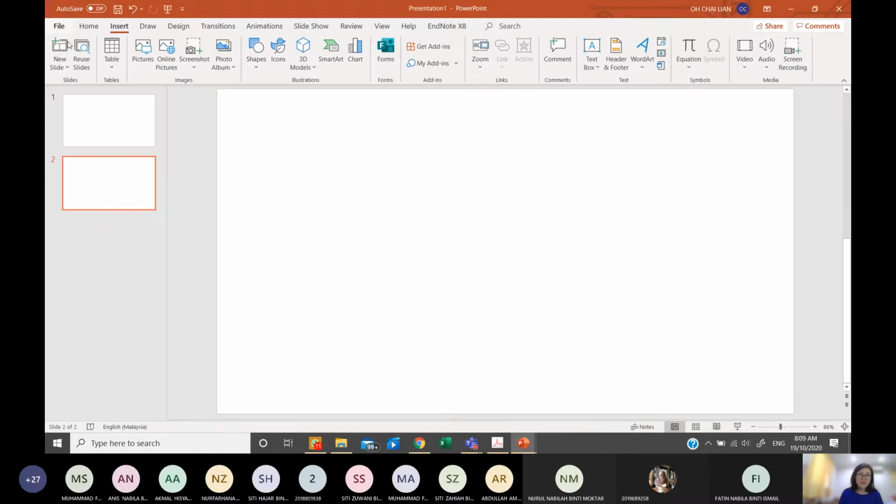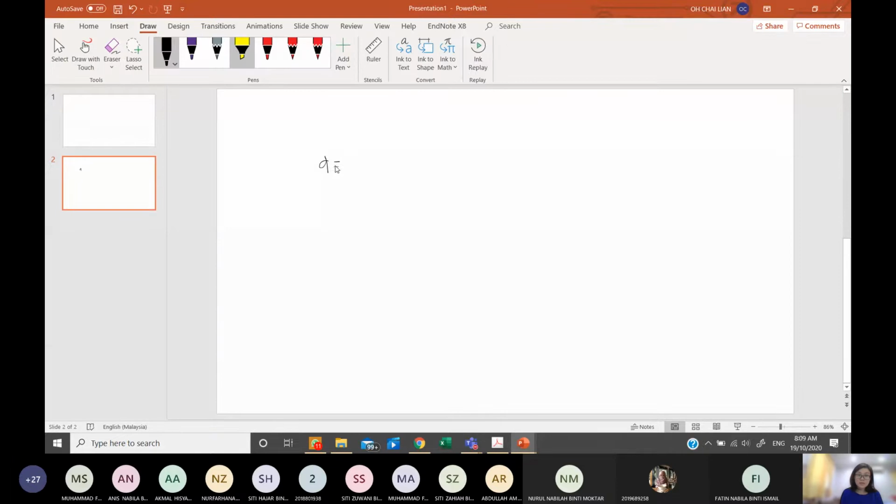Okay, maybe I will just write it again. What is D? For the beam, just now I heard you helping me: D equals R minus N minus C. R is the support reaction, N is always 3 for a 2D structure, and C is the hinge, the internal hinge.